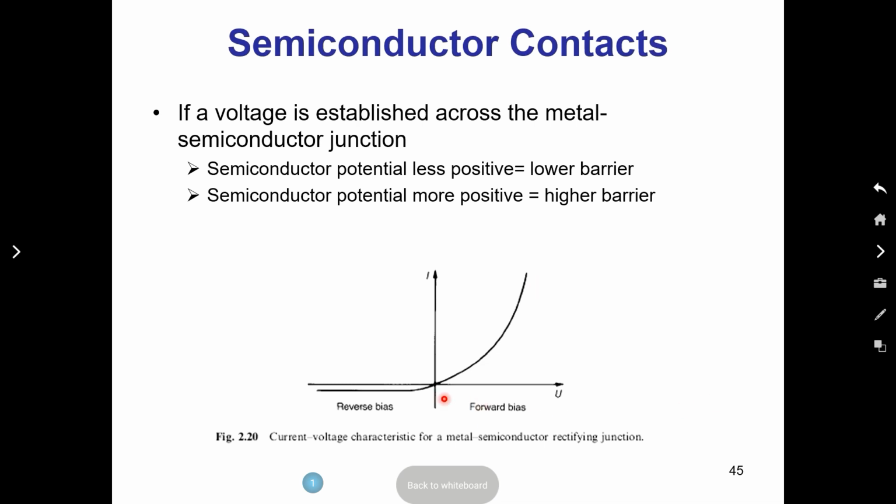Non-linear IV has to do with, in fact, this is not a good drawing. It shows that up to a certain applied voltage, this is supposed to be voltage, there will be zero current because of the Schottky barrier that is created at the contact. But for an equivalent amount of voltage, the current will start. Okay. So what people do is use the Schottky barrier as a gas sensor.